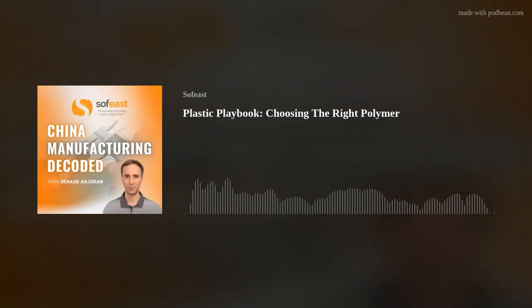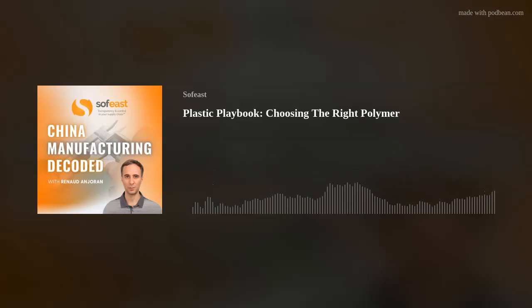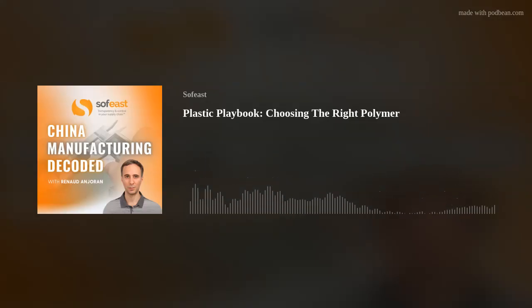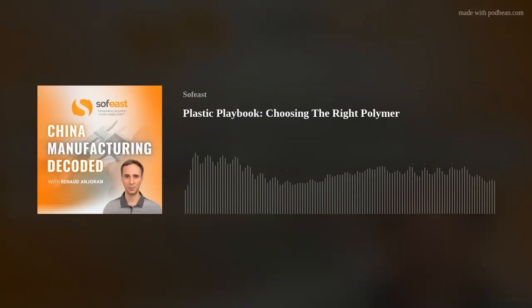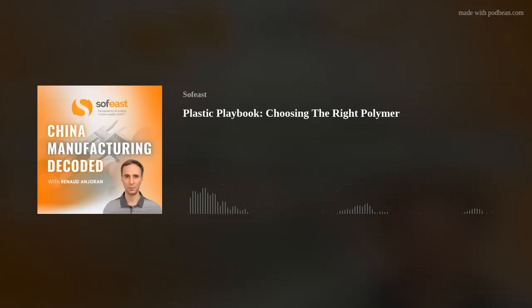It has to come with a polymer base. So that polymer base then has the additional material in. In other words, what we talked about earlier, a blend. So the blend here is the polylactic acid as the polymer. Then we are adding various different fibers in order to make that polymer a biodegradable sort of product, which is really, really important in some applications.